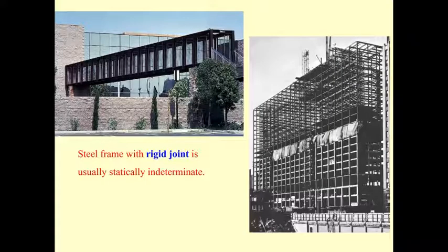Next, coming to the steel frame. Okay, the steel frame, this pedestrian bridge across the road, is built as a kind of rigid frame, as we just mentioned before. Ajahn, this is supposed to be the truss. No, this is the rigid frame if you consider it. For the truss, the frame is supposed to have diagonal members. If this one is the truss, the truss will be different from here.